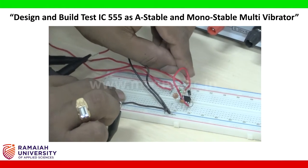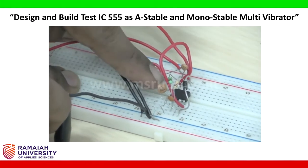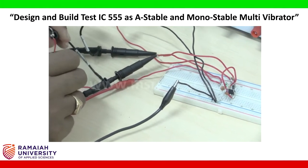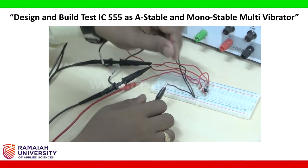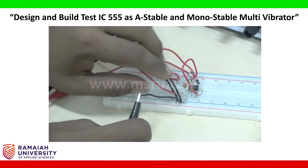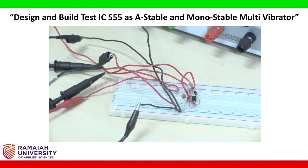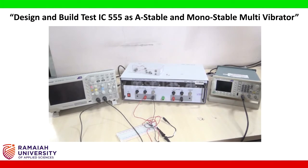Take the patch cord to connect the input from the signal generator. So this is the input of the signal generator terminal. The positive end will be connected to the capacitor, the one end which we are leaving free. So you connect that to this point. The negative you made into ground. This completes the circuit connection of the monostable multivibrator.